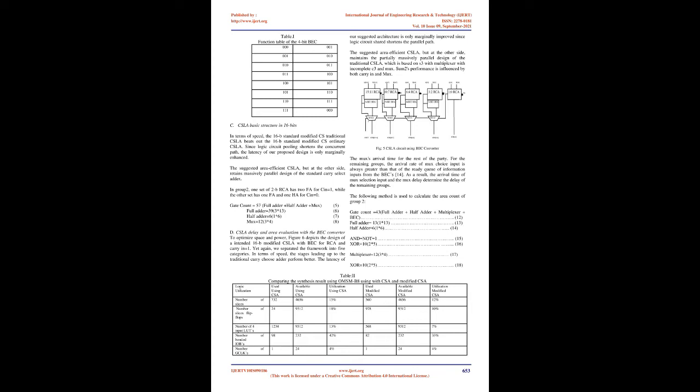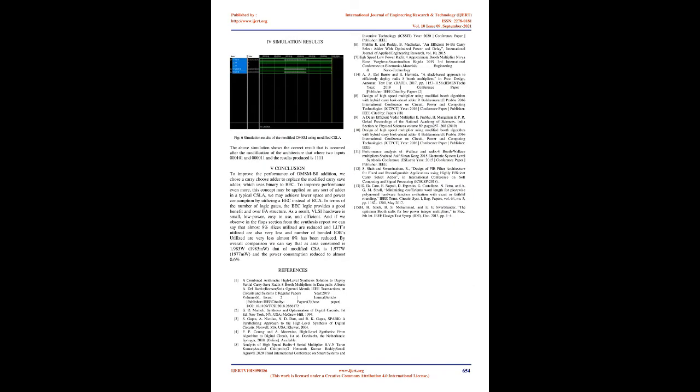In a conventional carry select adder, an RCA arrangement produces a pair of consecutive sum words. One of every pair is chosen again, for the eventual sum and carry. A traditional CSLA has a lower CPD than that of an RCA, but the dual RCA has a higher CPD, which makes the appearance unattractive. After so many unsuccessful attempts, it was decided to use one RCA and one add-1 circuit rather than 2 RCAs in the CSLA design. In terms of speed, a traditional carry select adder outperforms.